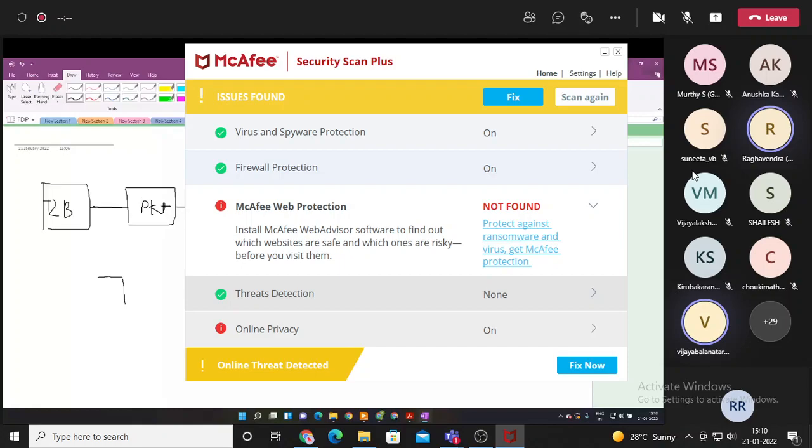Now, this will definitely work, as in the signal will definitely be captured. But the problem is, let's say I switch on my transmitter for 3 seconds, which is basically this duration, and then I switch it off. This is your off state, meaning the transmitter is no longer transmitting anything. You can notice that the 0 during your transmission state is the same as the off state. Meaning the receiver will not understand if you're not transmitting or if you're just sending a bunch of zeros, and it will just decode that.